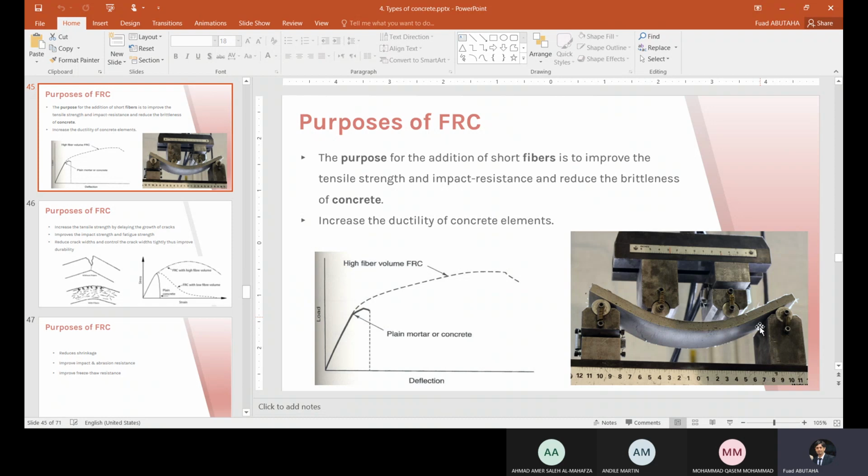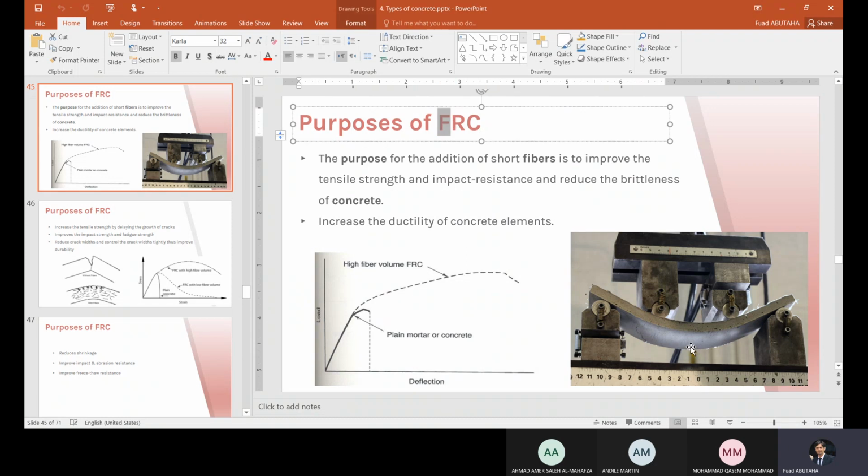The concrete doesn't have all this deformation, all this plasticity. When you go to the lab and use one prism of the concrete, it will suddenly break, brittle. When you start applying the load, at some point the concrete breaks into two pieces without showing any deformation like this one. But this is after we use the fiber inside the mix.